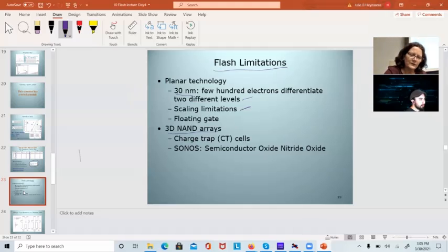Take one silicon array of NAND flash, stack it on top of another array, have through silicon vias on this part of the device, and then this layer is almost like a silicon printed circuit board that's making sure that these through silicon vias actually connect together. And then they can run the bit line or the word line vertically through the array, and so effectively address a larger number of strings at the same time.